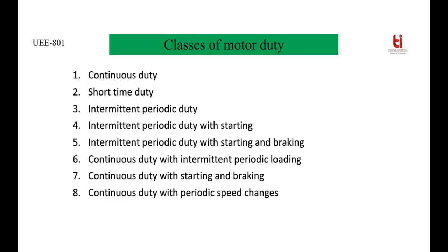Because of that increased current, the temperature rise will be more. Though the heating time constant is very large compared to the electrical time constant, its effect cannot be ignored. That's why intermittent periodic duty with starting is also one class of motor duty.